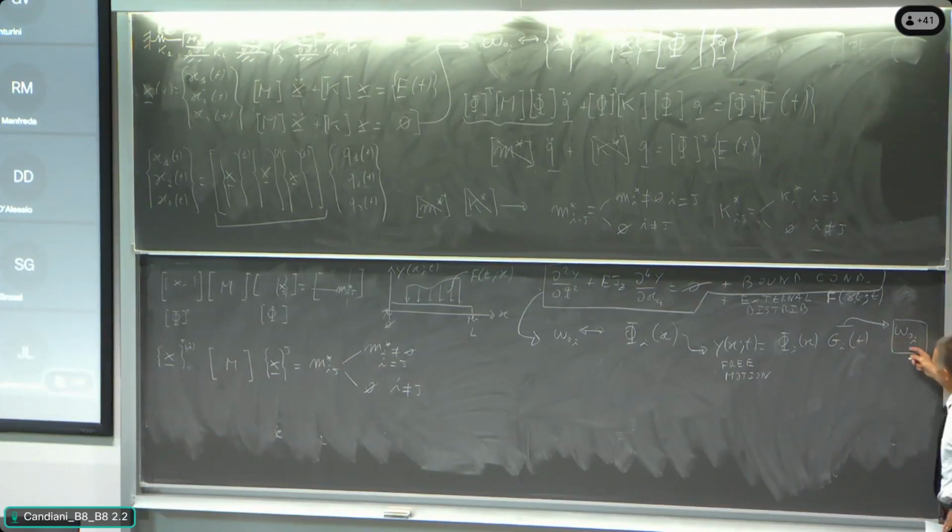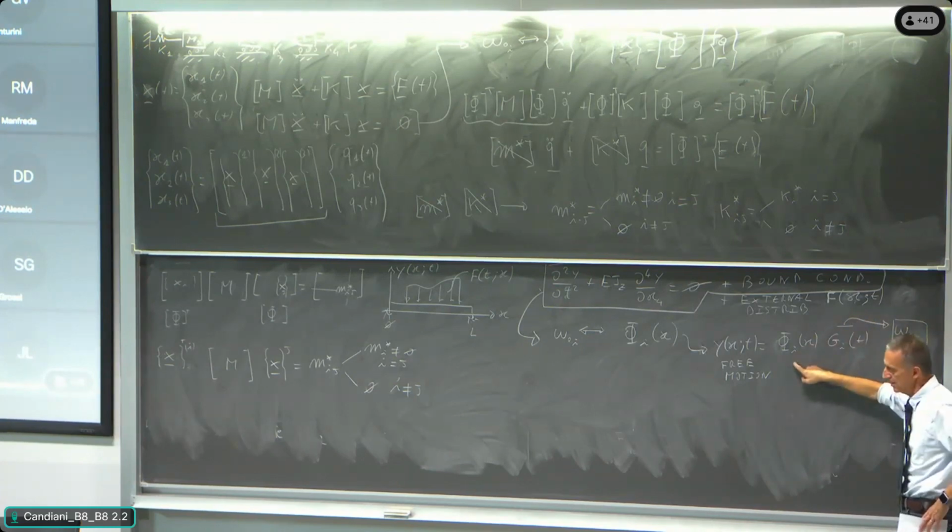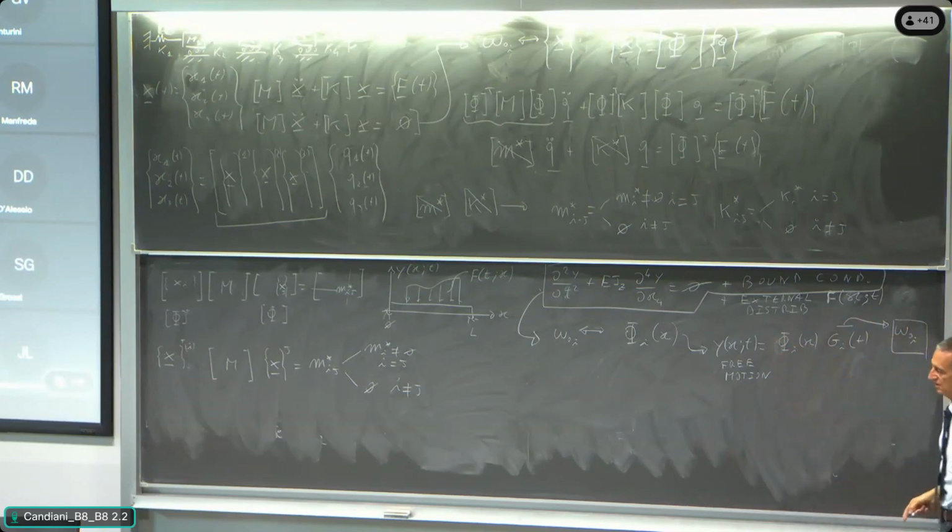We are finding out the natural frequencies that are making null the determinant of the matrix of the coefficients of the homogeneous problem. And associated to each of those natural frequencies, we are defining a function of space that is the modal shape of the specific mode associated to that object and to those boundary conditions. And we have a very clear idea that this function here is a harmonic function that is running at the specific frequency of the mode. All right? This is clear for us now.